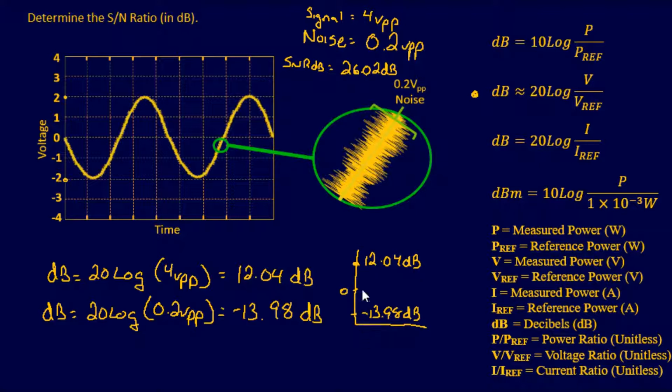So if you want a little visual aid here, you want to travel from here to here. We talked about in the PowerPoint, there's a reason you want to convert things to decibels. Because as soon as you convert to decibels, all you have to do is add and subtract. It's pretty simple. So we want to go from here to here. Well, it's pretty easy. If you want to go in this direction, all you have to do is take your signal and subtract your noise. And that will give you your signal-to-noise ratio just by adding and subtracting your decibels. So I'll show you.